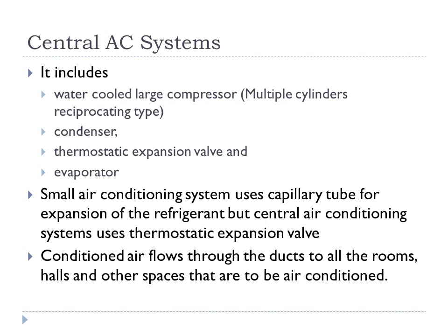So since the cooling requirement is high, we need to go for large compressor, and the large compressor might be this kind, that is multiple cylinder reciprocating type. Perhaps you have seen a car engine where we use multiple cylinders. So similar arrangement is also used for designing a compressor with large capacity, with large compression capacity. And since these compressors do a large job of compression, so they are water cooled.